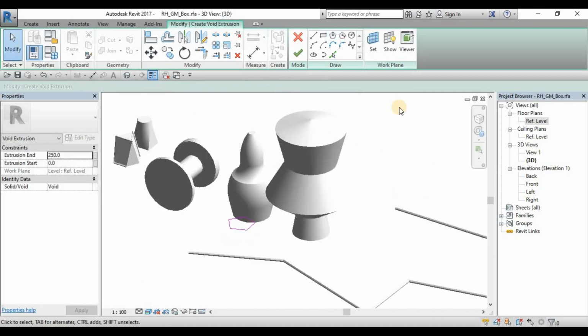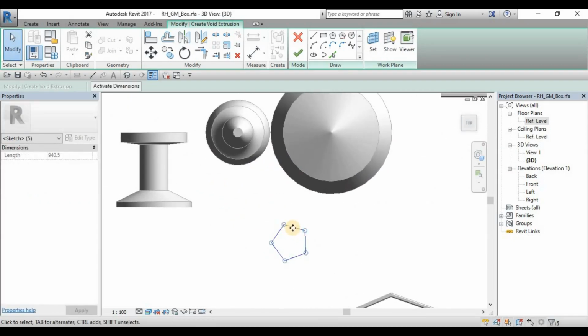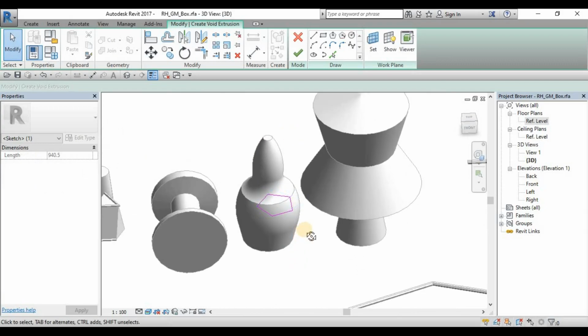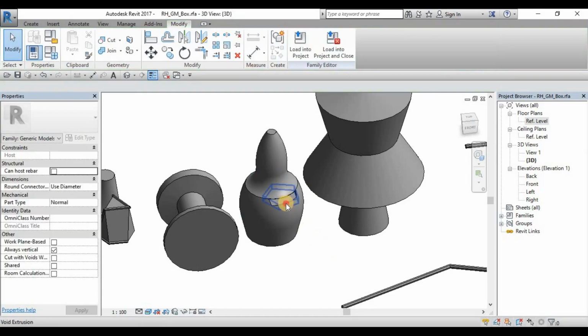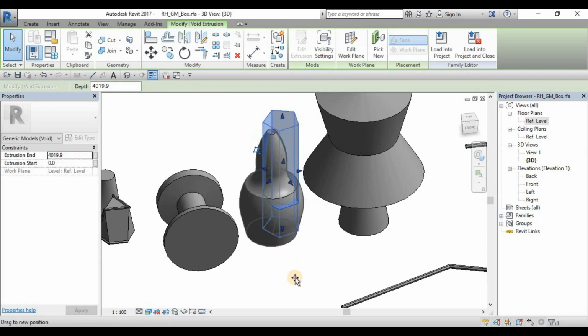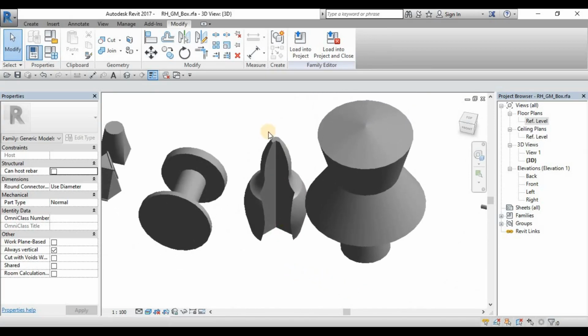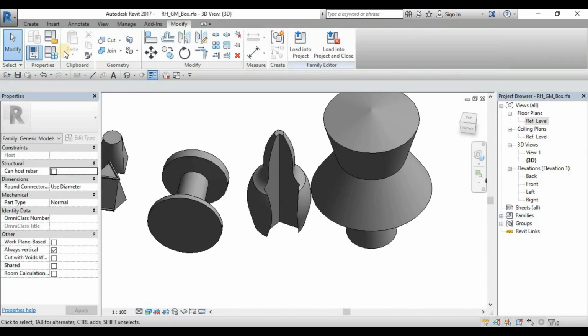There you go. Then just to make sure, I'll switch on my view cube, and then top part, yep, so it's quite far, so I'll just have to draw it from there, and then orbit from it, and then I'll finish. Yep, so this is your void. There you go. So it's cutting through this 3D object. So that is void.